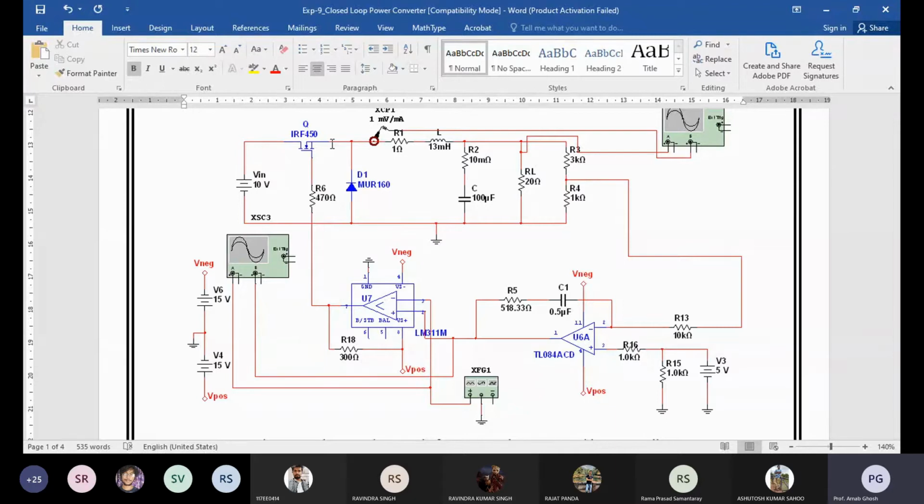Okay, so if your speed is varying, the actual input is coming from your motor speed, so that also varies. Basically the reference value is fixed, and the actual signal is varying, so your error will be varying. The differential amplifier compares your reference and that actual value. If the error is varying, it is passing through the controller, so the control output also varies.